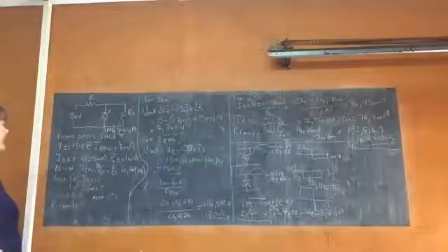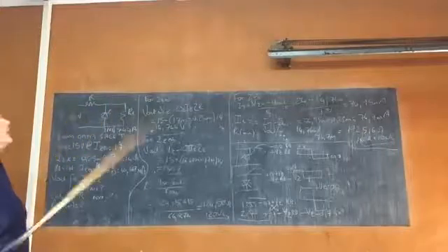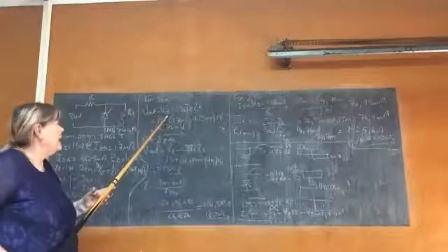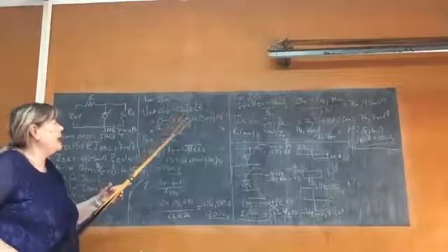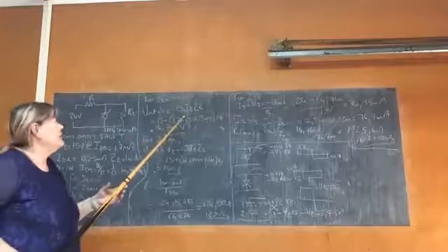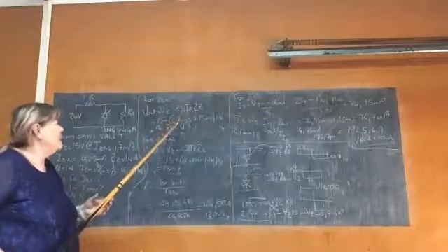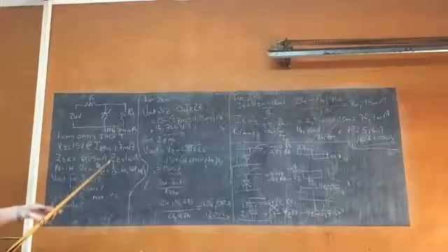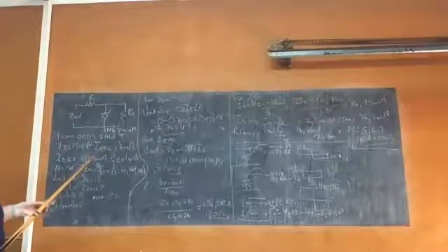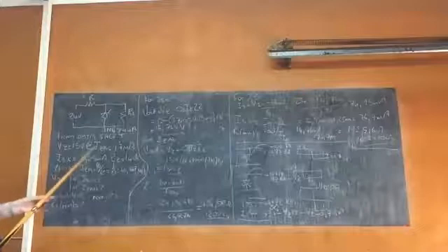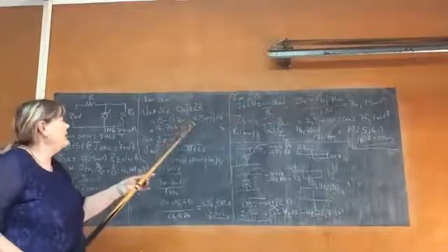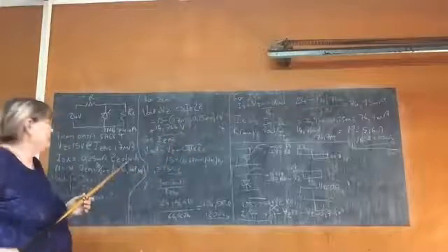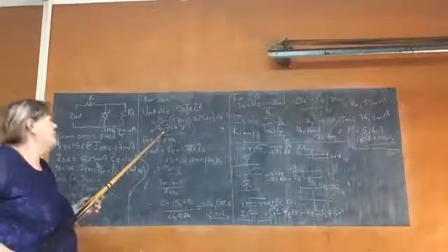Right, now, let's start. My V out for the minimum IZK: I have my formula, VZ minus delta IZ times ZZ. Now, delta IZ is the difference between my IZ and my IZK. So it's IZ minus IZK times 14, the ZZ given. And I get a voltage.